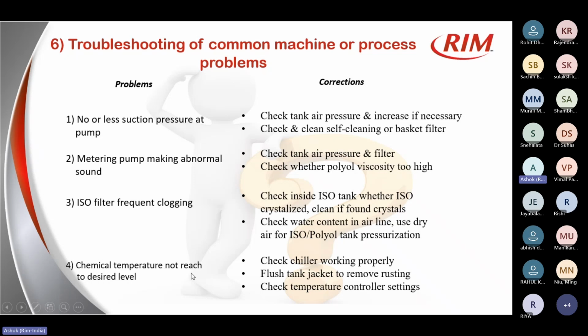Chemical temperature not reaching the desired level. So the chiller capacity, or whether the chiller is working properly, has to be checked. If you are using the machine for a quite prolonged period, then you have to periodically flush out the tank jacket using some descaling chemicals. Then your temperature controller also has to be checked.